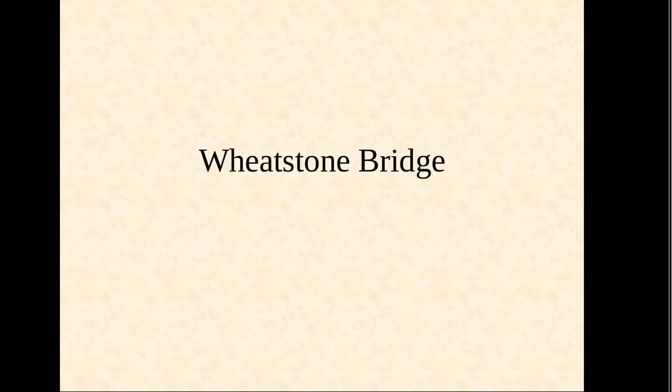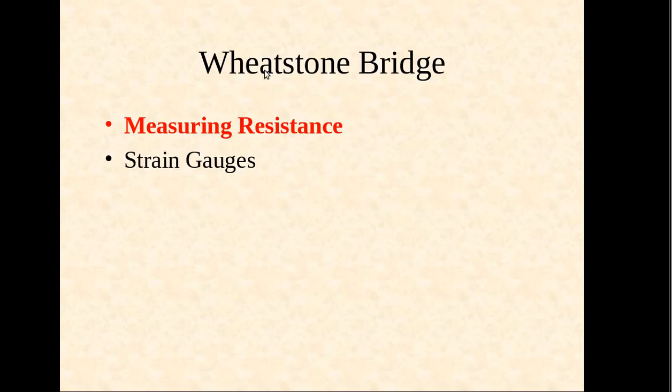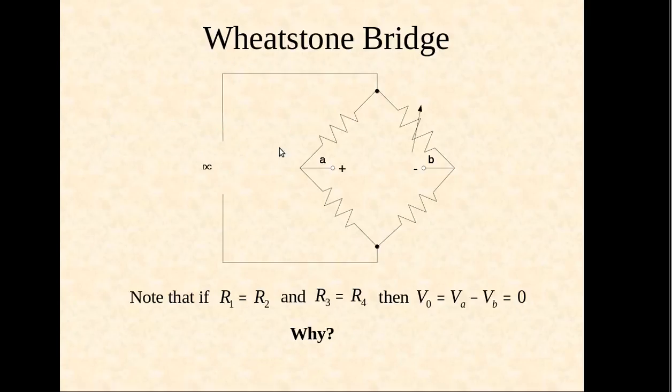It is a very useful bridge that we can use to know unknown resistance, as well as we can use this same bridge for temperature measurement, weight measurement, by knowing the unknown resistance or the parameter that is missing. So here in the Wheatstone bridge, we will go first for measuring resistances. As you can see here, it is basically the circuit diagram of a Wheatstone bridge.